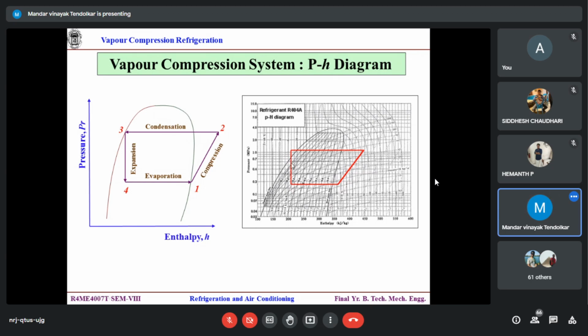Like this, if you draw, then this is the subcooled part. This is the saturated liquid, and its left hand side means liquid. So this is subcooled, correct? And then you start the liquid expansion. Initially it will expand and reach the saturation part, and then it will enter into the two-phase zone. So the design of this process is very, very difficult. Liquid expansion. Gas expansion is simple, and this is the reason we do not use the turbine. How will you expand the liquid in the turbine?